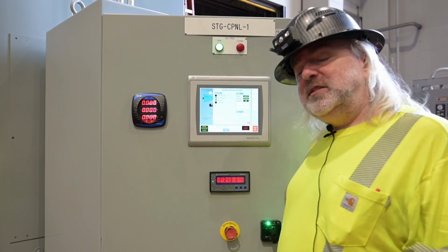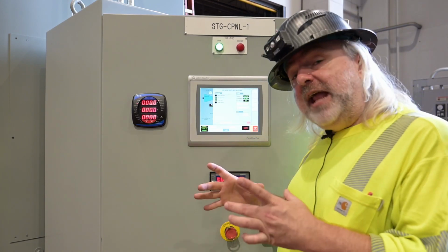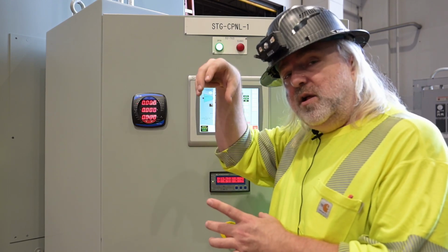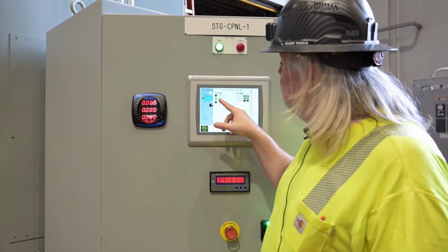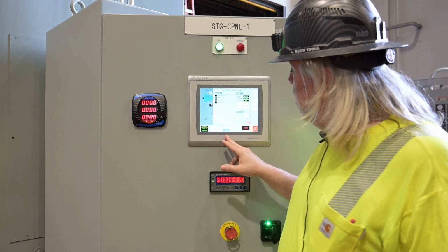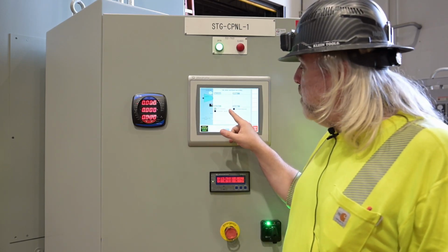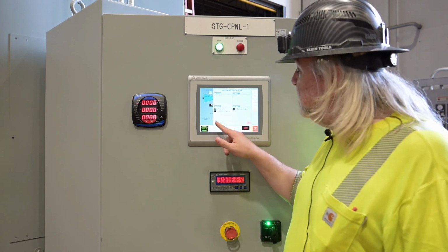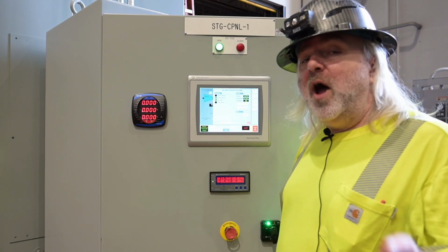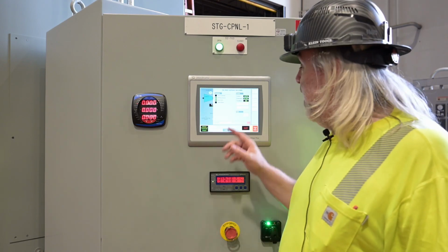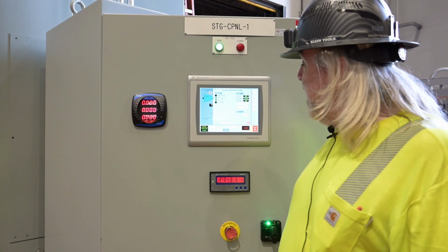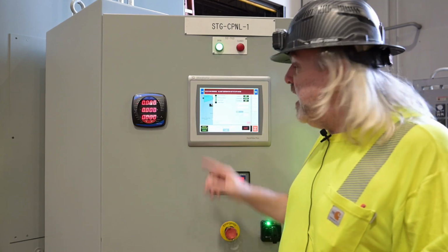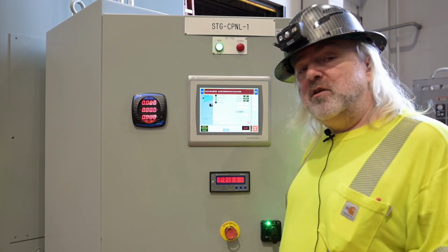Oil mist fan. This is the oil mist fan. There's a little canister with a fan above it that's drawing air out of the oil system through the canister. So this fan will always run if the aux oil pump or any oil system is operational. As long as the system is in auto, the fan will run when necessary. Again, you can turn it off at any time, and if you turn it off and it needs to be running, you'll have an alarm: oil mist separator not in auto.